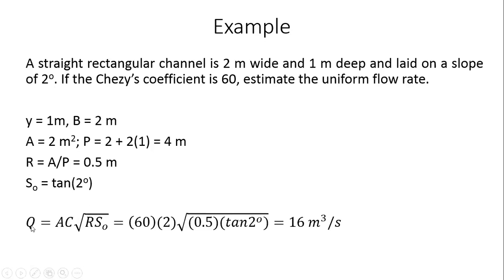You can simply solve for Q. Q equal to A times C times under root R S naught. You put in all these terms, you get 16 meter cube per second, right?